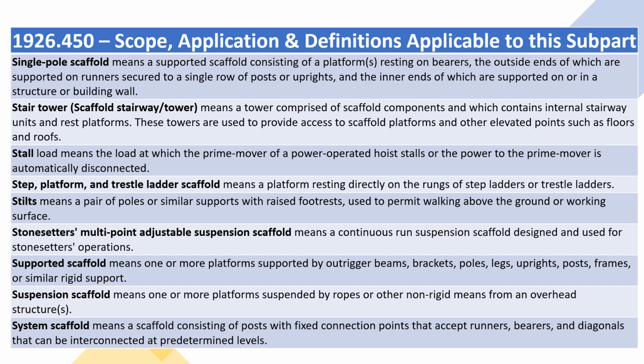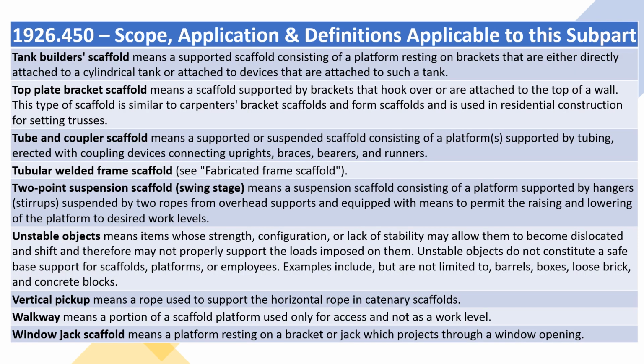Supported scaffold means one or more platforms supported by outrigger beams, brackets, poles, legs, uprights, posts, frames, or similar rigid support. Suspension scaffold means one or more platforms suspended by ropes or other non-rigid means from an overhead structure. System scaffold means a scaffold consisting of posts with fixed connection points that accept runners, bearers, and diagonals that can be interconnected at predetermined levels. Tank builder's scaffold means a supported scaffold consisting of a platform resting on brackets that are either directly attached to a cylindrical tank or attached to devices that are attached to such a tank.